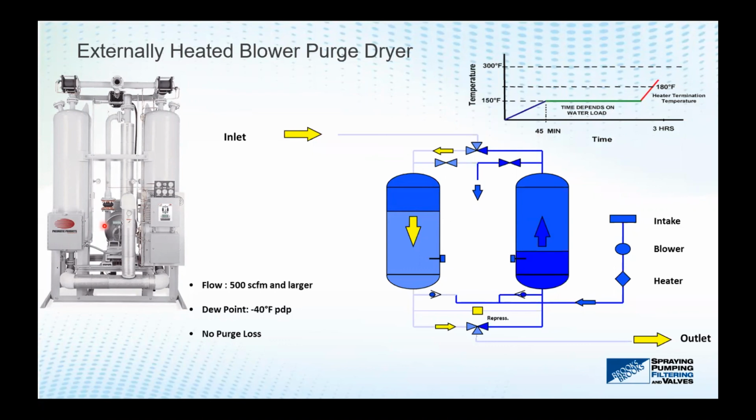So certain customers, instead of buying a new compressor, if they need more air, can just add this blower package to their heatless dryer and reduce the purge consumption. So one, it makes it more energy efficient, and two, you're saving yourself 10%. You're not buying a very expensive compressor, you're just buying a lower cost blower to increase the efficiency of your purification system.